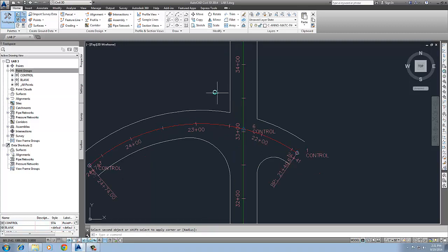We can come up to this side, do the same thing, just repeat the fillet. Radius is already set to 25. That's a 25-foot radius. Pick and go. And what we have here is now a reverse curve. The one curve going this way, the other going the other way. And remember, the radii are on opposite sides of a common tangent, which is somewhere around in here.